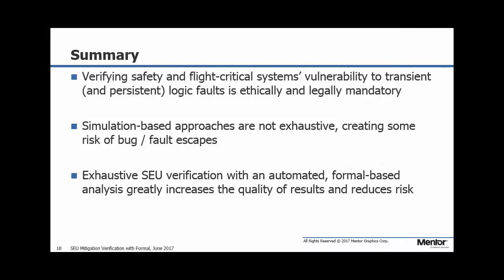Simulation-based approaches are not exhaustive. So formal obviously has that advantage over them, but they also take a fair amount of time and effort to deploy. On the other hand, applying formal verification to this problem is exhaustive. It tells you exactly which faults are safe and which faults will propagate and gives you the counterexamples so you can debug it. And this increases the quality of your device and reduces the risk of having a catastrophic failure.